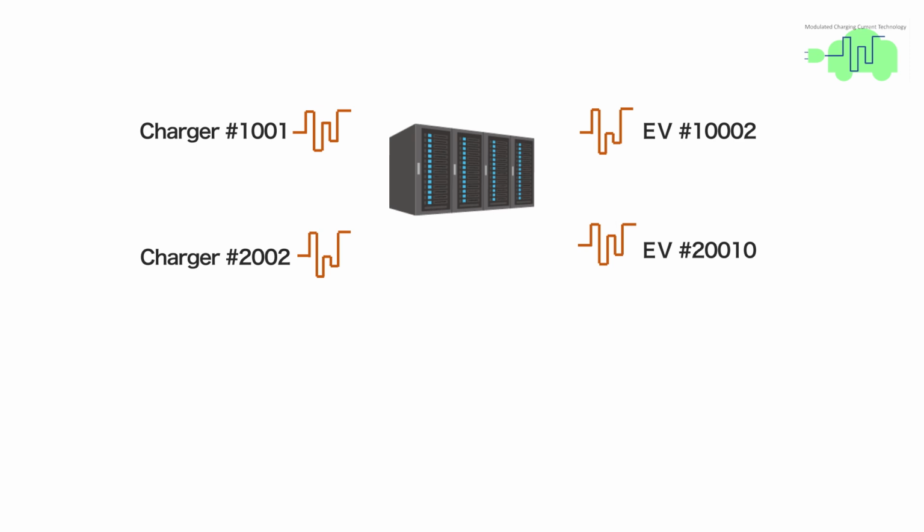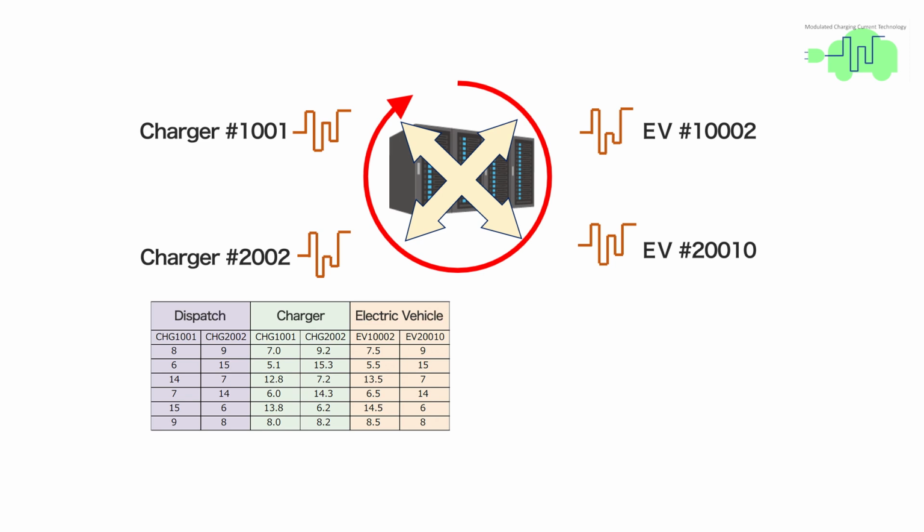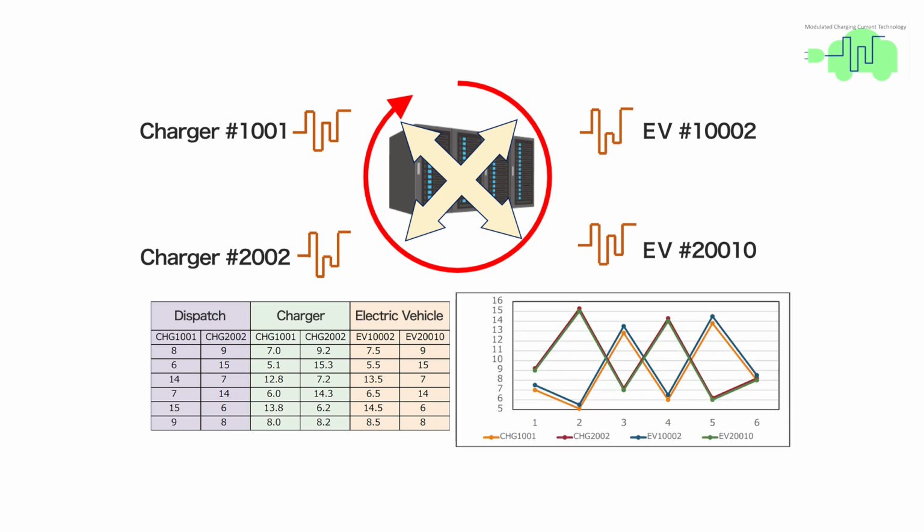The current values obtained in the experiment are shown. By checking the matching of these four patterns of current change, the combination of connections between two chargers and two EVs can be identified. The matching sequence is performed in this experiment using the cosine similarity method. Various methods or combinations of methods can be applied to perform the matching sequence.